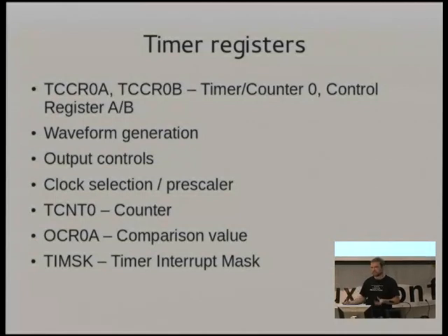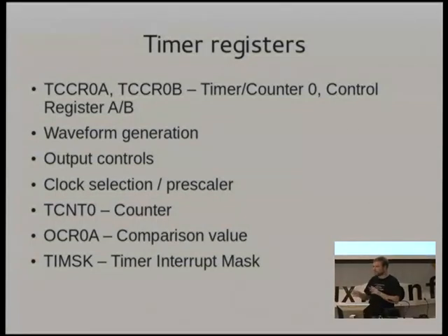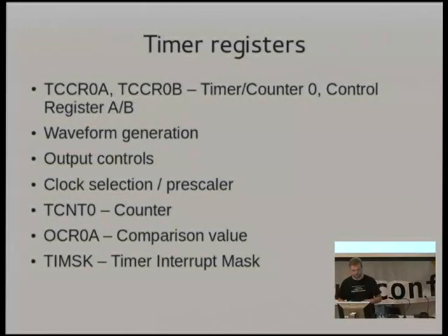So there's a series of prescalers which basically just divide the clock by that speed and let you slow down that counting. Between choosing the overflow or comparison values and choosing a prescaler, you can actually pretty closely map to most real-world times that you might care about.